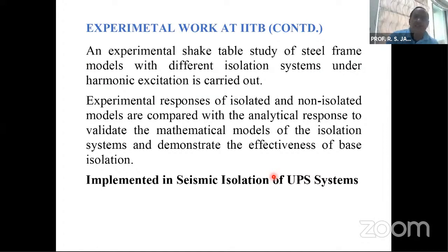The excitation that was considered for the shake table was harmonic as well as some simulated earthquake motion, and experimental results were then validated through mathematical models, and it was observed that there is a good comparison between experimental and analytical results. Finally, these isolation systems which were developed, though very small in size, were implemented in a UPS system for the nuclear structures.